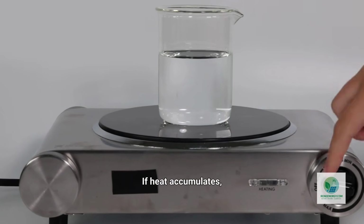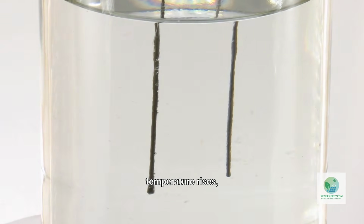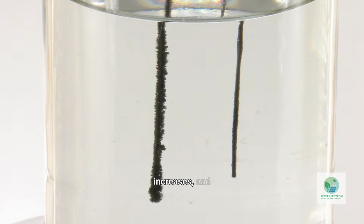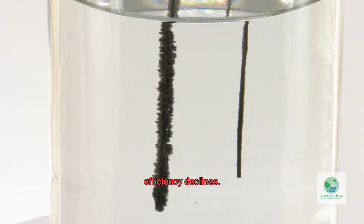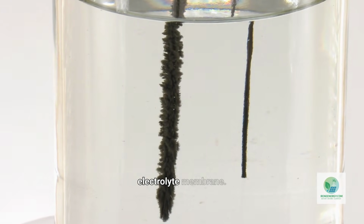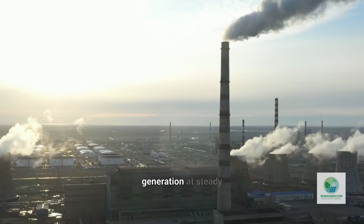This is not optional. If heat accumulates, stack temperature rises. As temperature rises, membrane resistance changes, voltage increases, and efficiency declines. Prolonged elevated temperatures accelerate degradation of the polymer electrolyte membrane. Therefore, cooling capacity must match heat generation at steady state.